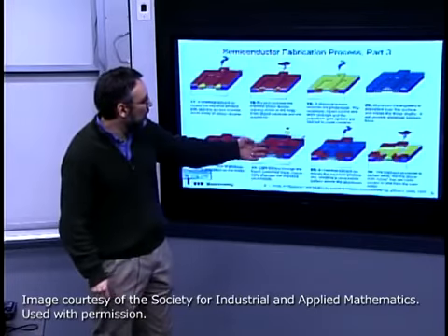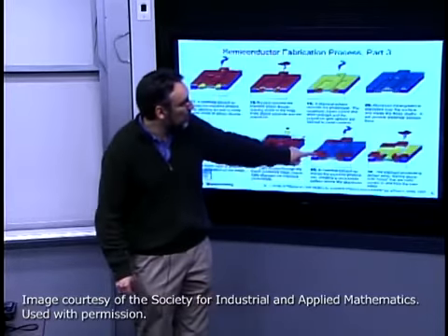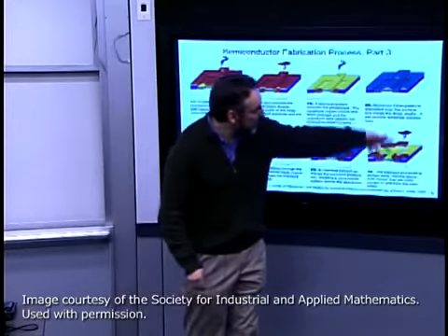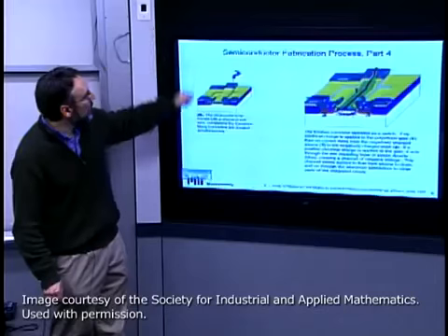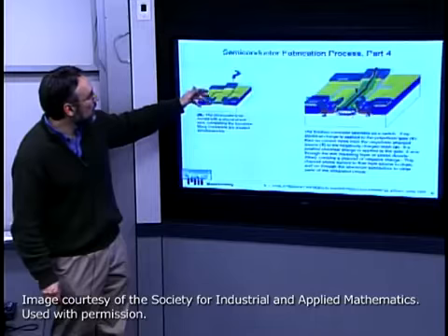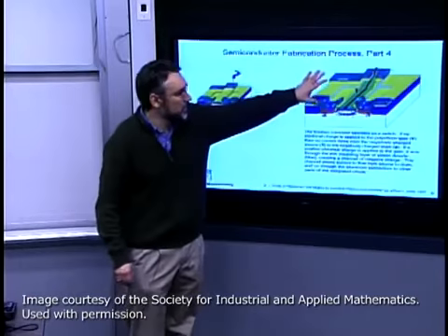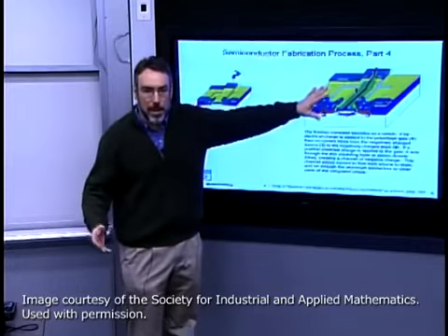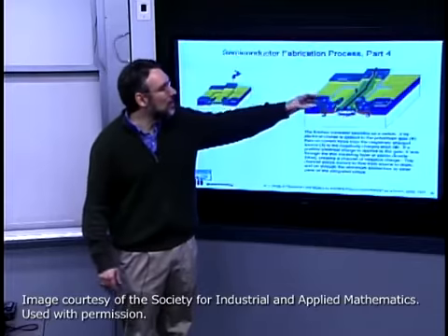So the basic idea is now we've covered the whole surface of the wafer, and we selectively go in with a photolithography step and remove where we don't want the metal lines. I've protected where I'm not going to want to etch. So I'm protecting parts of the aluminum, and then I do a plasma etch or a chemical etch in order to remove the aluminum, and then I strip away the photoresist, leaving my structure. Now this is a single level metal, very simple transistor in building up a several billion transistor chip, or even 100 transistor chip.